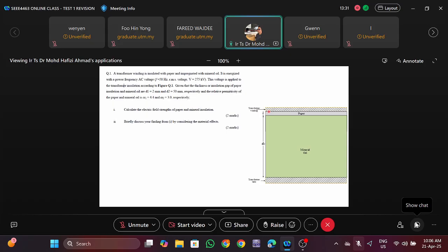So as we already learned in chapter 1, when we have different relative permittivity, we can have electric field displacements. Okay, so the electric field becomes non-uniform on the interface between these two different materials because they have two different relative permittivity. So it's like a light that might be refracted. Okay, and then on the surface of these two materials, we have what we call tangential electric fields. So this kind of tangential electric field is very, very dangerous. So we can increase the electric fields, and the electric field becomes nonlinear, especially on the interface.